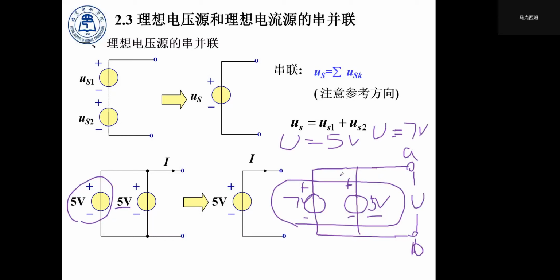But if you put some extra resistor in it, that could stand. But you can't put two ideal voltage sources in parallel with nothing in between. Two parallel-attached voltage sources with different values are not acceptable. We don't do that, since we create a paradox.